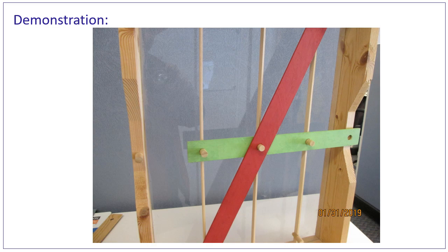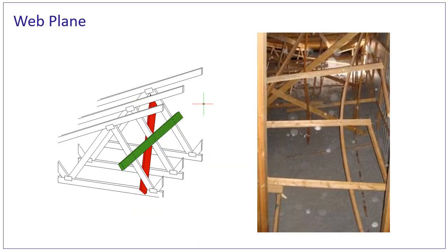When you see a lateral restraint, you should also see some diagonals. The diagonal and lateral work together to transfer the required forces. The photo on the right shows what can happen when not installed correctly. Keep in mind that the diagonal should cross the lateral where the web is at.